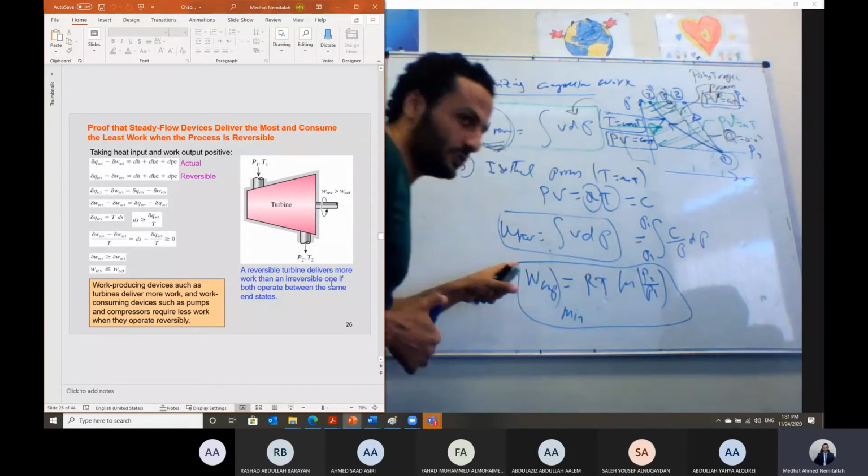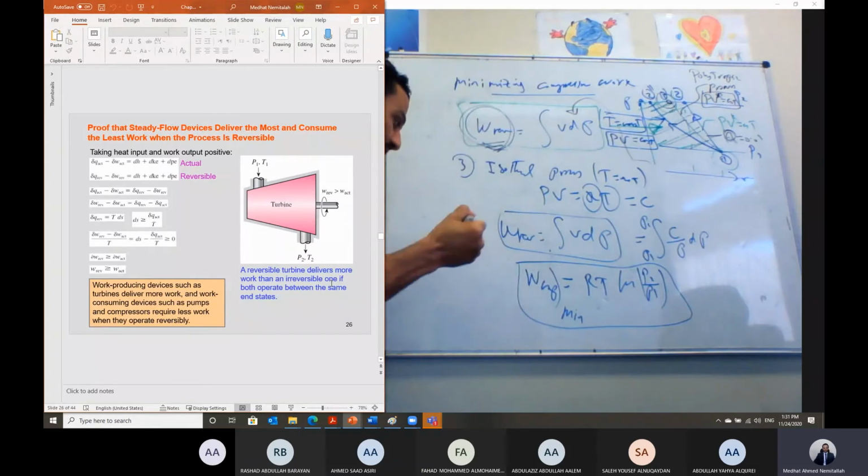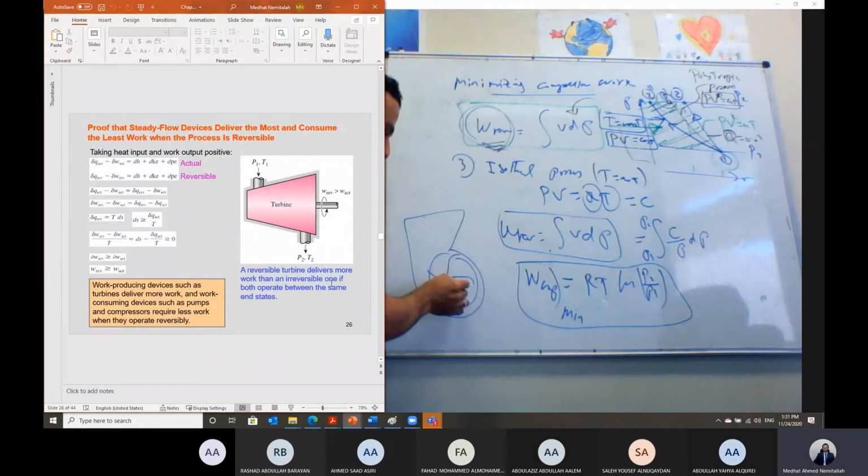But can we make the process isothermal, Shabab? In reality, we have a compressor like this. We have blades here. While the flow is going through the blades, the area is decreased in the direction of the flow, so the pressure will be raised and the temperature will also be raised. That means if I'm using an external water jacket here, it will do nothing much.